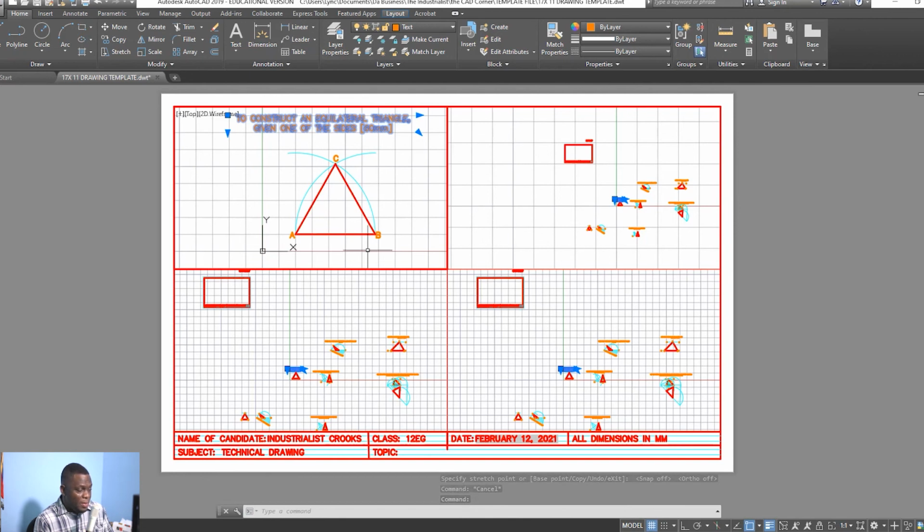Then what I'm going to do is move this heading to the paper space. All my headings and all my lettering, I'm going to move them to the paper space so that they're basically set and they have no chance of moving or shifting, and they'll be one constant size. So I'm going to press escape, select it, and type CHSPACE. So, change space.